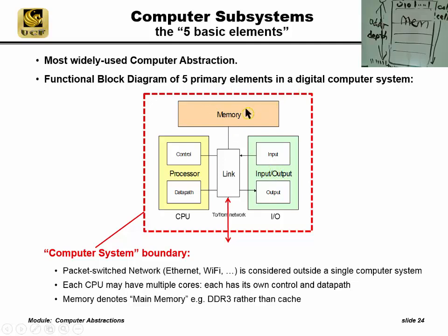Memory stores bits, processor crunches bits. It uses 2 separate circuits, a control circuit and a data path circuit, that work together. These are the actual bits that are flowing that get changed. That's the data or data path. And the state machine that increments the program counter, we saw the program counter getting incremented to the next instruction.